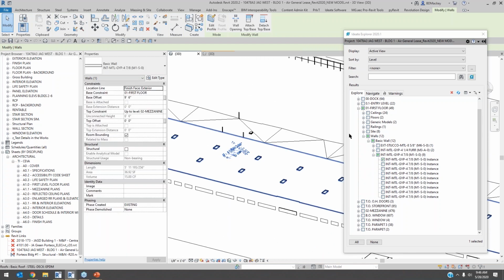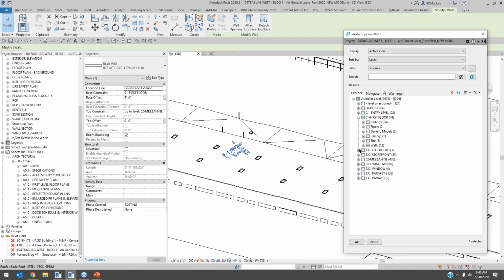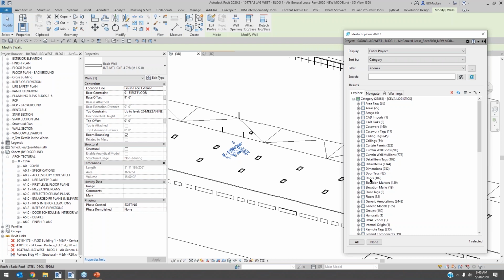object. So I use this a lot to start QAing the model, and I know there's tools in the BIM Link. I'm talking somewhat about the BIM Link today. I know there's tools in the BIM Link scenario that allow you to do it, but for me, just using this to explore, navigate, and start going through. Well, I think, and Brian, since you just mentioned it too, is the fact that just like Style Manager, you can have it open, you can work, and so you can use any Revit command once you select things. If you wanted to isolate those or by a view or something, you have the control to do that.